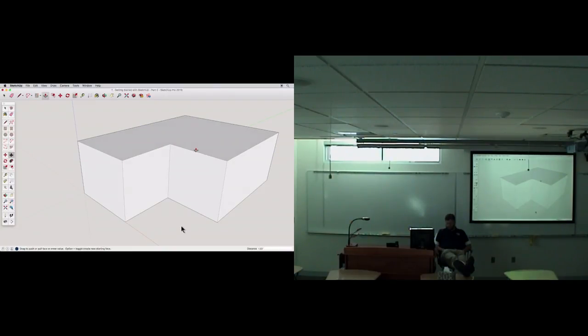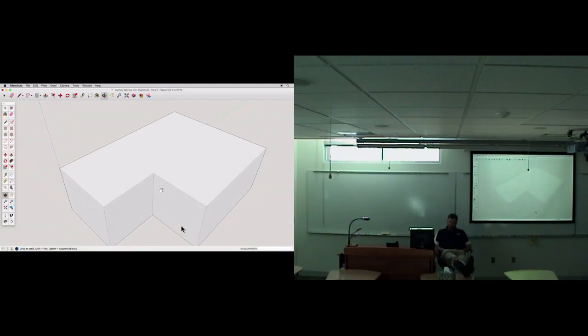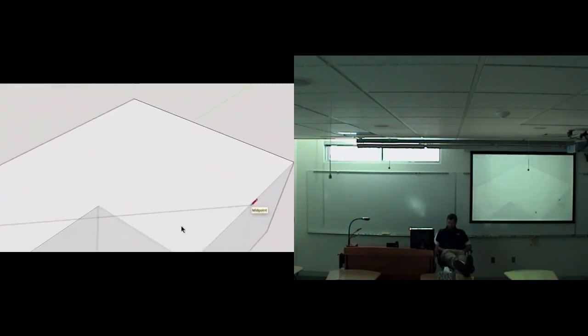To create the roof, we'll use the line tool and draw all the edges we need before pulling the ridge up. Using the line tool, find the midpoint and draw back in the green direction. This will be our first ridge, and we need to connect it exactly to the second ridge. To do this, simply hover, but don't click, on the midpoint here, telling SketchUp that we are interested in this